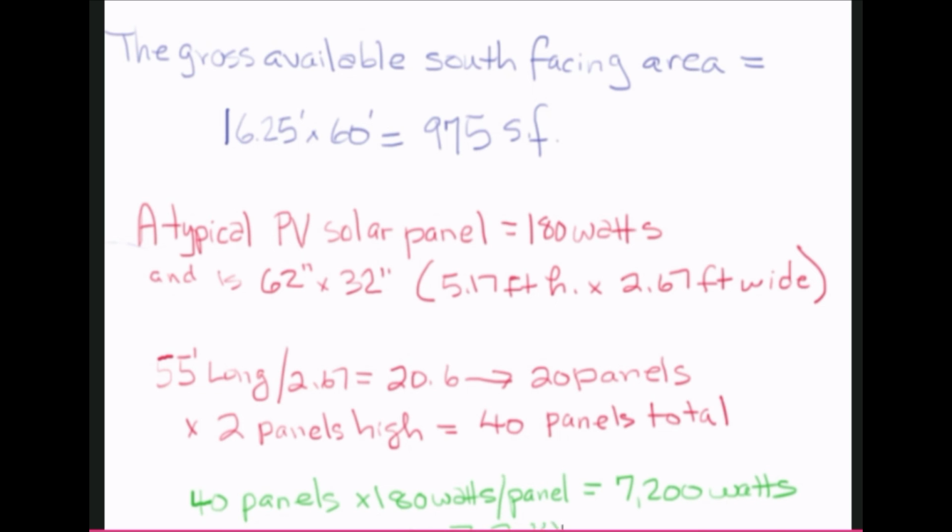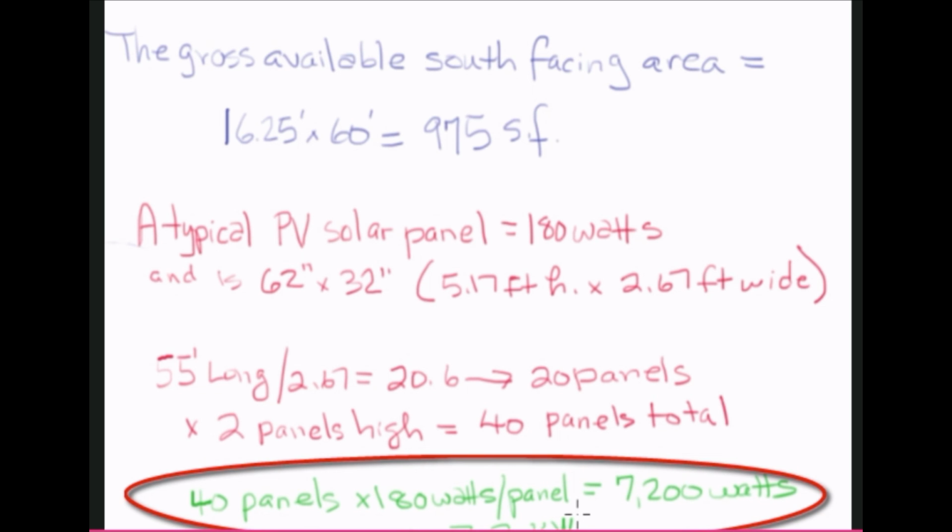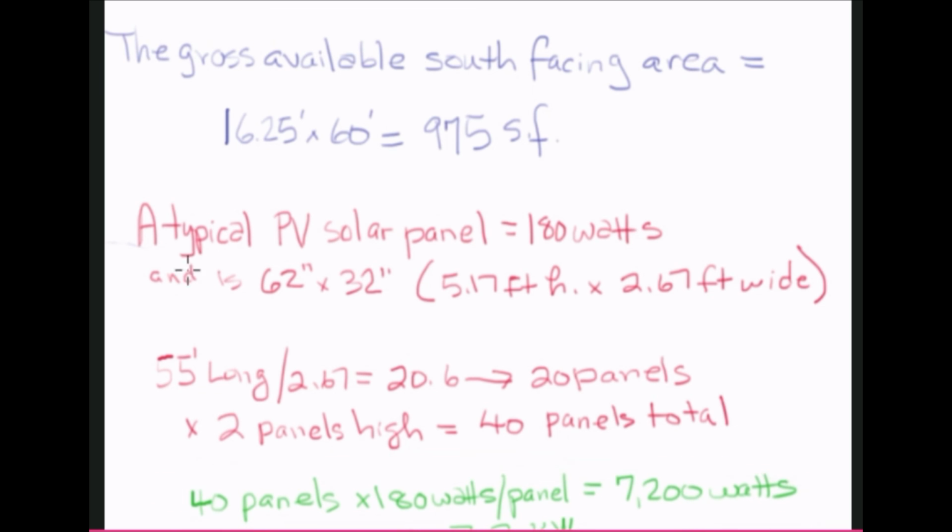Although this number is slightly lower than the peak requirement at 11 o'clock on the 23rd of July of 10 kW, it's a good illustration of how you can use knowing the area of the house, knowing the output of a panel, knowing the incident sunlight on a given day, you can calculate the total area required and the total output of a PV solar array for a particular residential application.